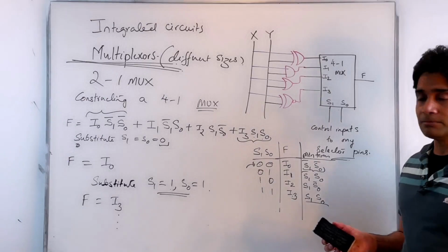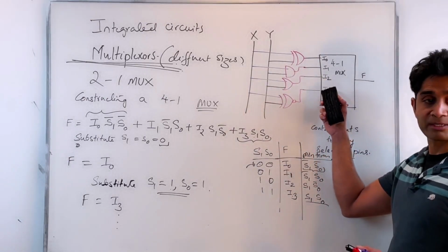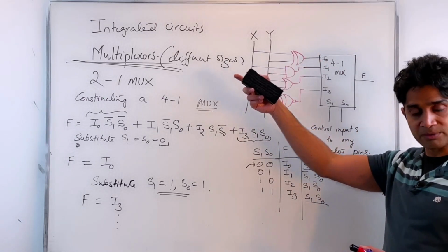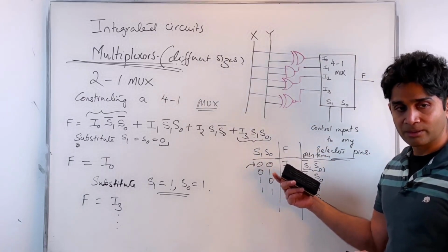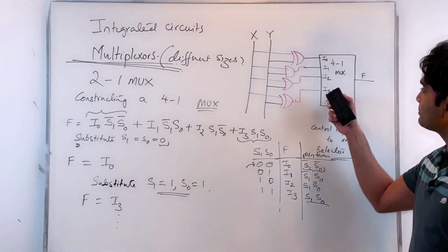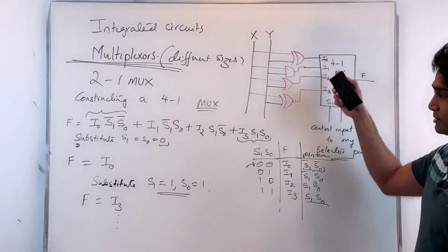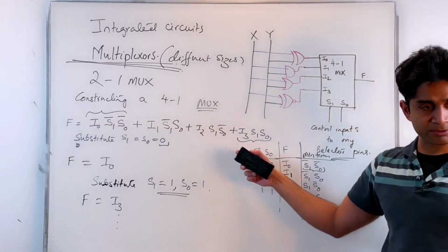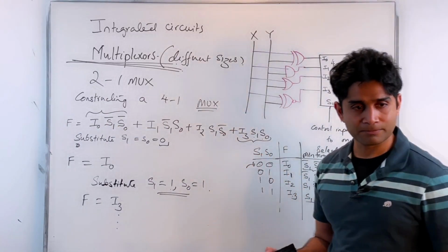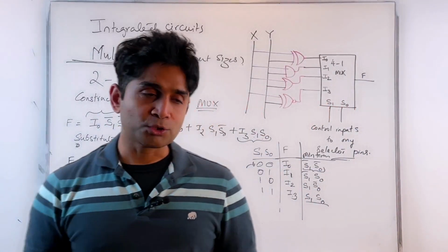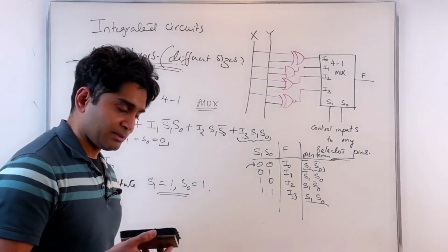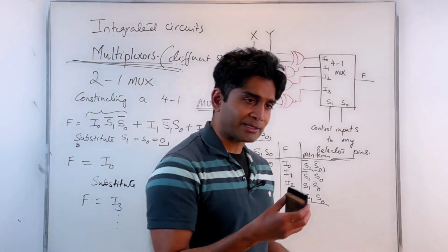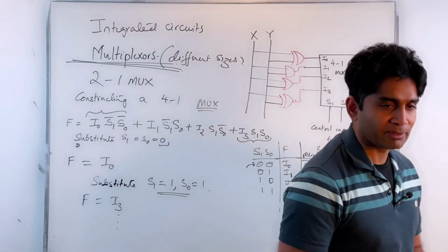So now we have seen how we can use the multiplexer in our design to multiplex between different operations. What is the internal construction of a multiplexer? If I want to look inside how it is constructed at the fundamental gate level, that's what you would see, the innards of the multiplexer. Now what I want to do is, can I obtain any function, instead of directly using fundamental gates?